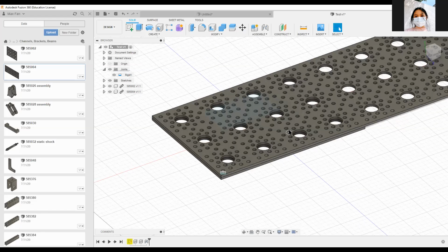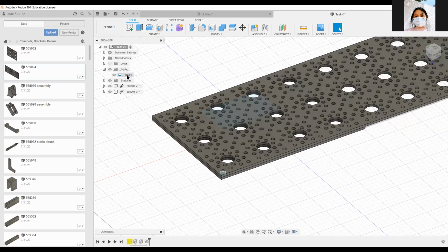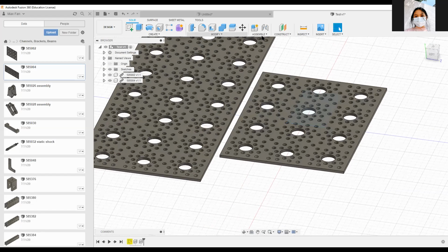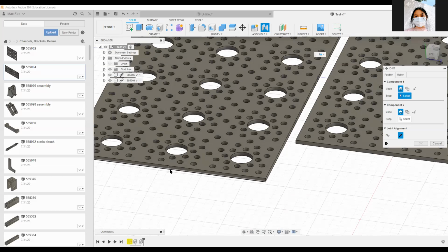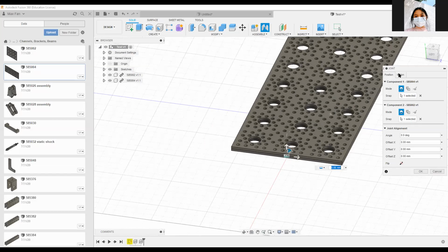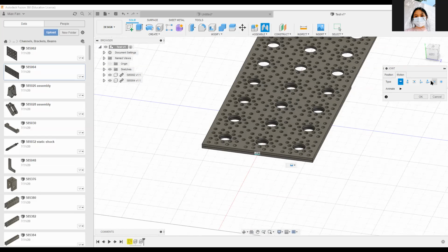So let's say you don't want it to just have this plate stay there, like just not moving. You want it to have some action. So in that case, there are different joints that can help you. So if I made another joint, I just selected this middle point and connected it here. So you can see in this joint drop-down menu, right next to the position tab, there is a motion tab. And with this, you can see that there are a bunch of different types of joints.